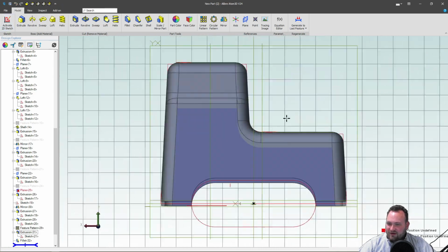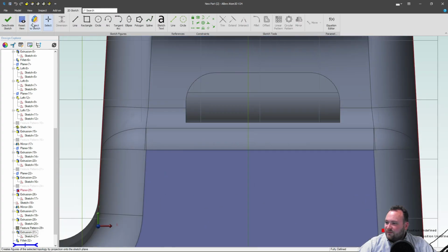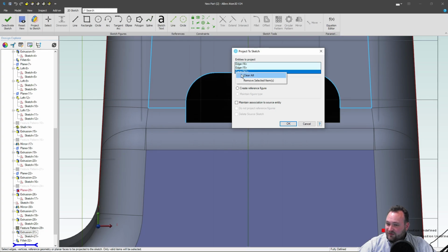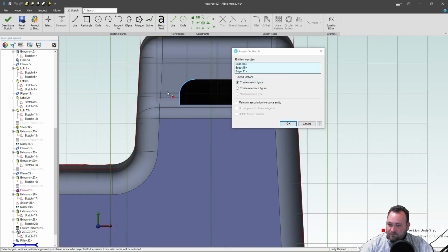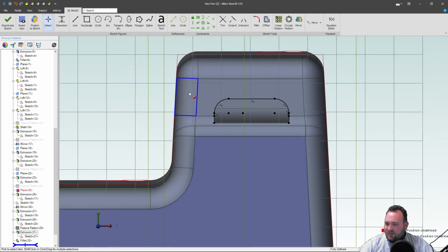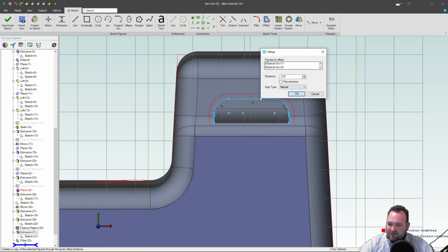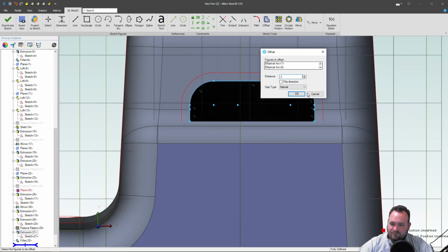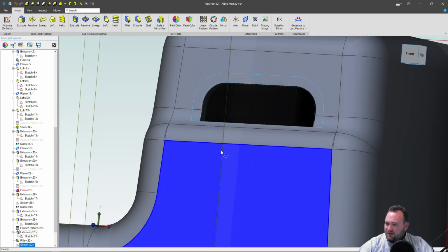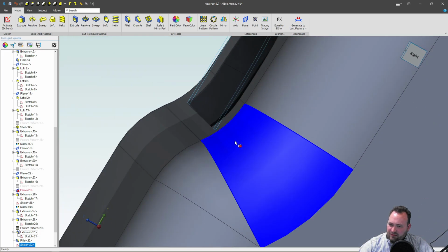So now, highlight this face, activate 2D sketch, and we'll reset the view. We'll project all these different line segments, but actually I just want the segments, not the face, so we'll remove that. We're going to maintain association, highlight everything. We'll go with an offset. How about 0.2? And if you're serious about all this, make sure that this gets fully constrained for the reasons that I'd mentioned before. Deactivate the sketch. Yeah, that should be good.